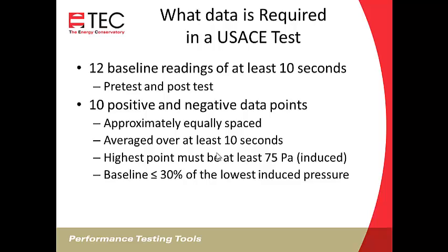And it does have a requirement that the baseline be less than or equal to 30% of the lowest induced pressure. So in the case of our test, we had a negative 20 for a baseline, which means we need to be at about negative 60 for our minimum data point. So we'd be gathering data from 60 pascals to 80 pascals in evenly spaced periods in that case. So we'd meet this standard.